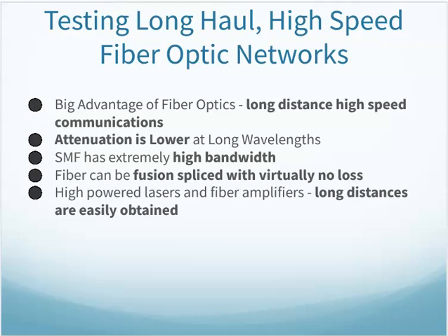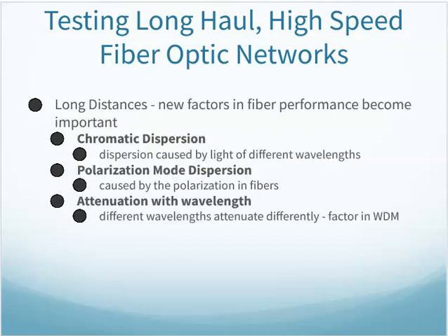Single-mode fiber has very high bandwidth. Fiber can be fusion spliced with virtually no loss, so you can have long distance cables with little loss. That's one of the advantages of all of our fiber optic. Now with long distance, there's new factors in performance that come into play.